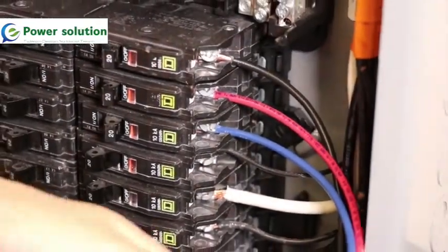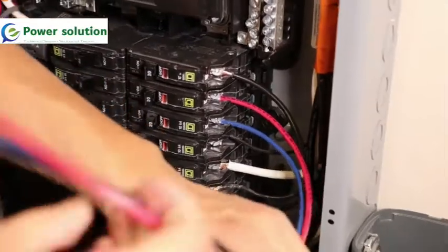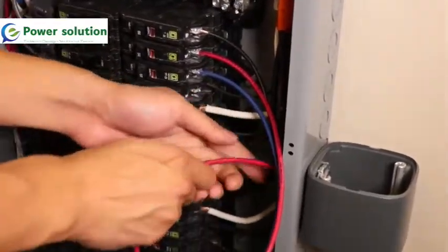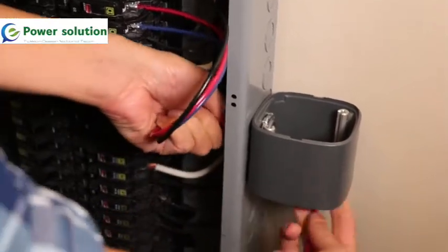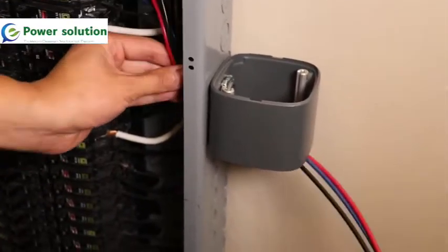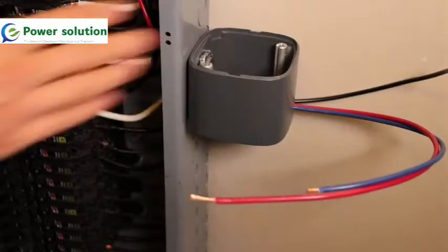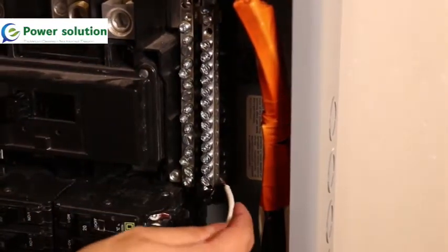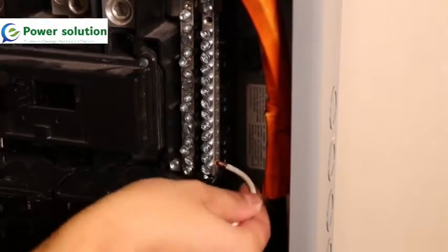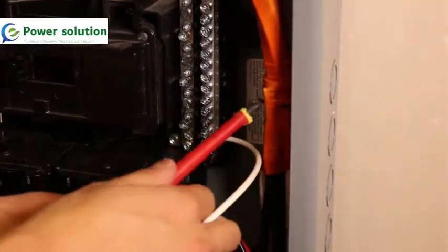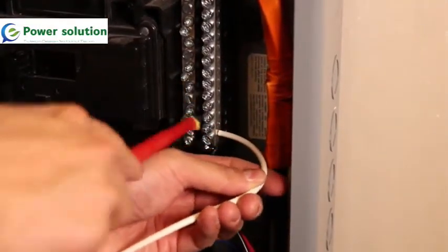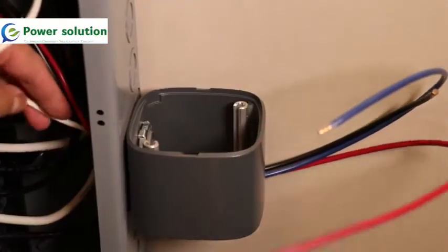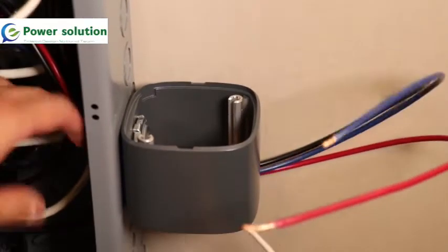After all the voltage phases are connected, we'll take our new voltage taps and feed them through the knockout that we just created and leave them here for us to connect to our base transmitter later on. And finally, we'll connect our neutral tap. We pick an open port on a neutral bus, thread our wire through, then tighten with a screwdriver. Now we're going to run our neutral line through the knockout again and bring it down with all of our other voltage taps.